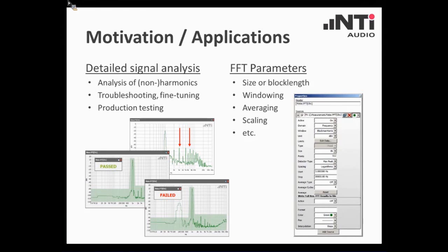Well, if you have ever used an FFT, you may know a couple of these parameters that are typically adjustable. The size of the block length, windowing, averaging, scaling, all these parameters and some others are very important to adapt the FFT to your specific application, to your demands. So it is of course essential to understand what these parameters stand for and how to use them properly. And that is what we want to show you in this webinar.